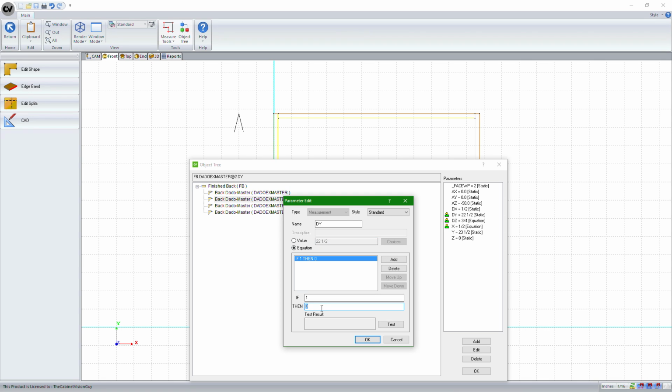We'll go back to our second one, go to our dy value, and set this to an equation now. We'll go parent dx, which if I look at it, is the 23.5, which is correct. We're going to subtract the value we just put in, and subtract that again, but remove this @3 modifier. That'll make it look to this first one in the list.